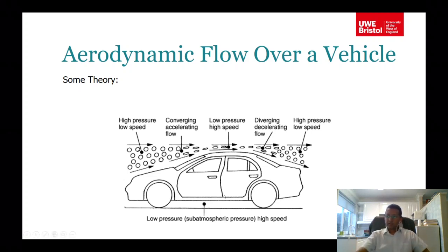That means you have a negative lift force here, meaning the force exerted on the car is downwards. That will help the car to stick onto the road better. In other words, it will increase the weight of the car in a sense, but that is good because when you have downforce like that, the stability of the car is better and the handling of the car will be better.